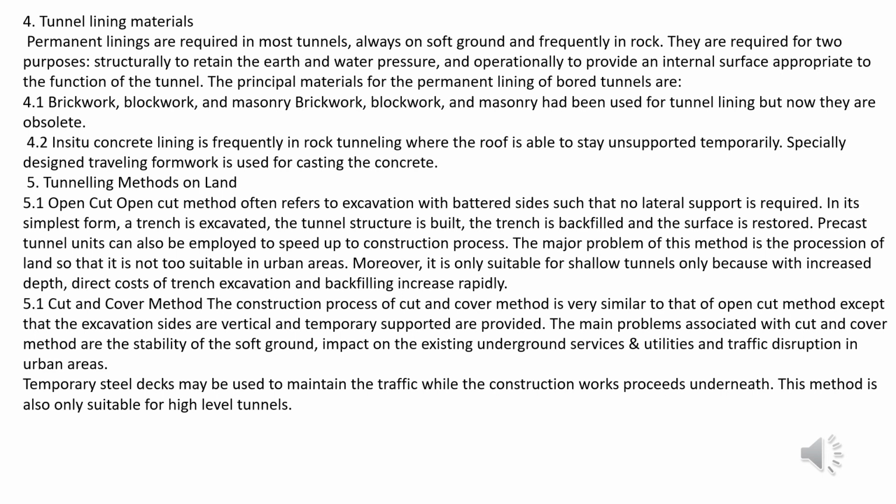Cut and cover method. The construction process of the cut and cover method is very similar to that of open cut, except that the excavation sides are vertical and temporarily supported. The main problems associated with the cut and cover method are stability of the soft ground, impact on the existing ground services, utility and traffic disruption in urban areas. Temporarily, steel decks may be used to maintain the traffic while the construction is underneath. This method is also suitable.